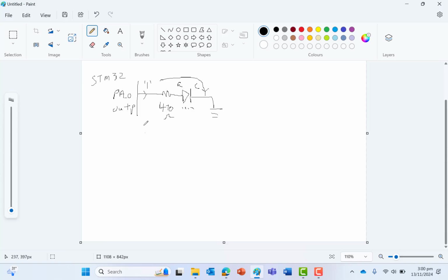This is one way. Now of course there is another way, which is to reverse the connection. You connect this way. Of course here now you need a high voltage, maybe 3.3 volt. This one is again a small resistor. Now you have to output a 0, for the current to flow from high to low, and the LED will turn on. So these are the two common connections. But always remember to put a resistor.